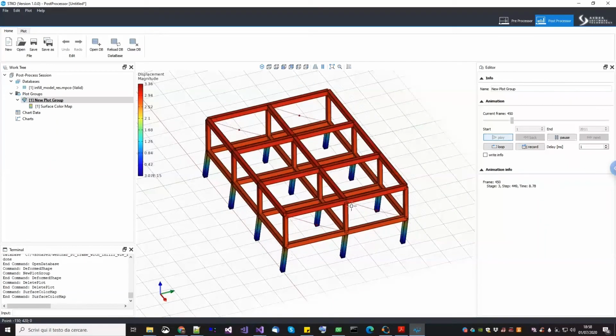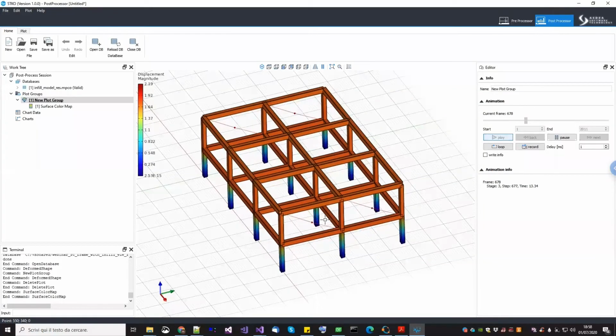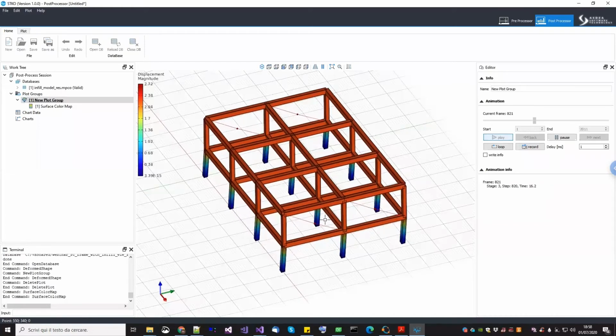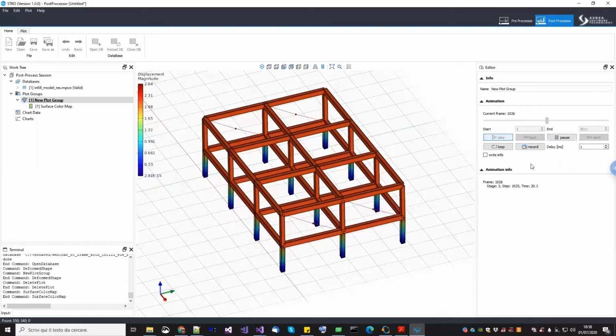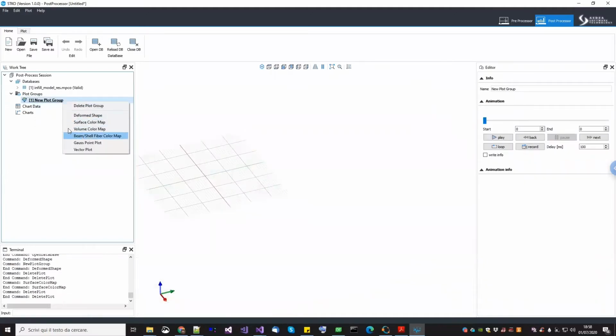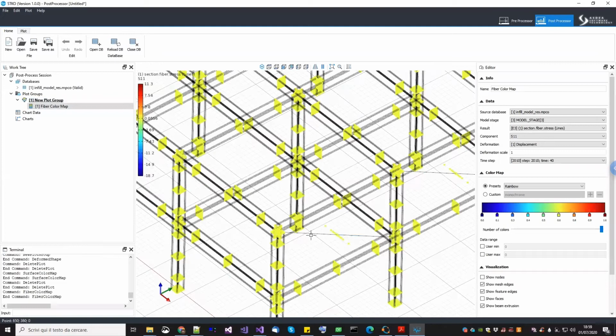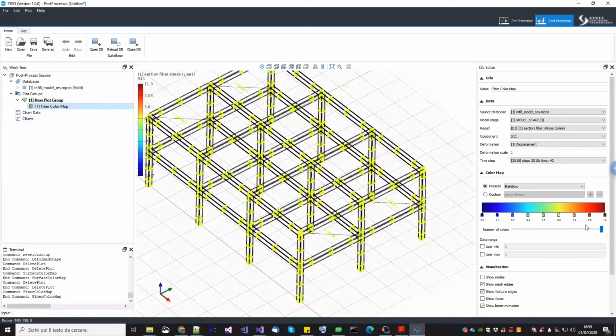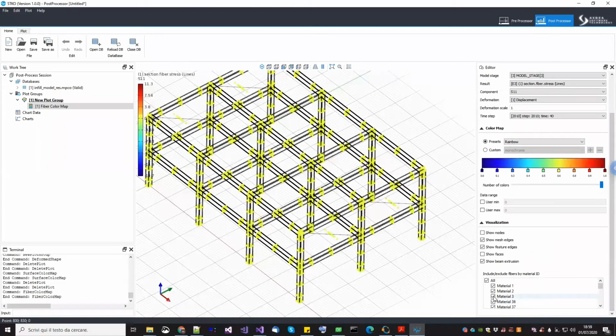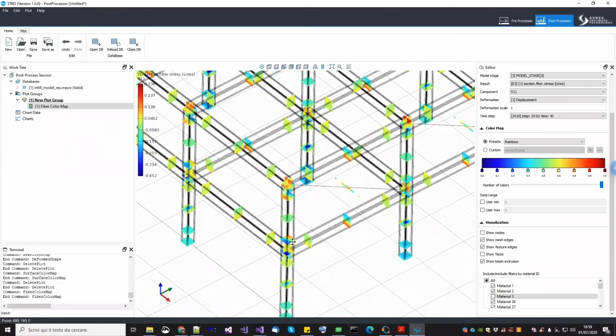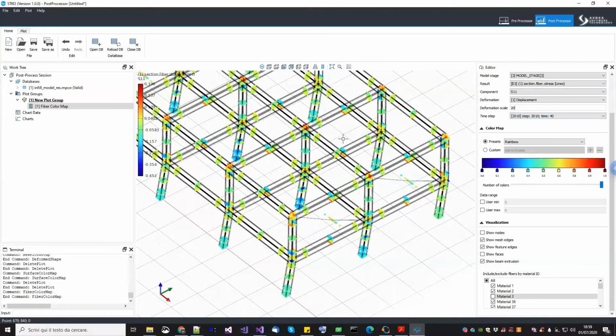Now, as you can see, the top one didn't fail with respect to the original model, because actually the material properties are different, because they were using material properties coming from smaller infills. That is one of the reasons why having an automation is better, because you avoid those mistakes. Okay, so we can also see what's going on with the fibers. As you can see now, they are slightly thicker here because we are using a larger infill with respect to what they did. And also in this case, for example, I'm plotting the fiber stresses. Let's say we want to switch off the steel, which is material number 3, so we can see the stresses here much better. And let's see what's going on at this level.